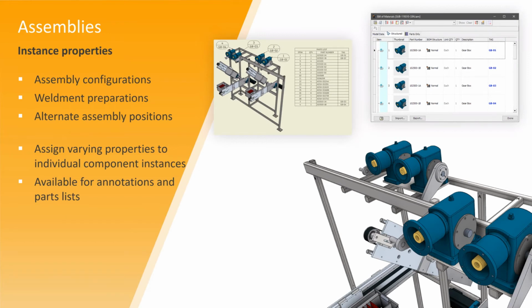When you open a legacy assembly that contains levels of detail, the following three system-defined levels of detail, all components suppressed, all parts suppressed, and all content center suppressed, are actually removed. You might remember those three system-generated levels of detail. For those of you that are familiar with that, they are actually deleted out of the system. And any that you've created yourself are, as I said, migrated across to model states.